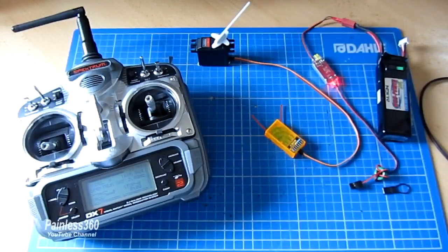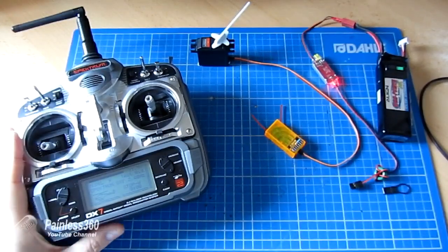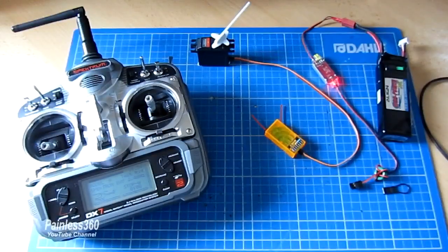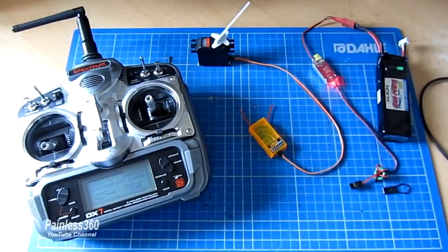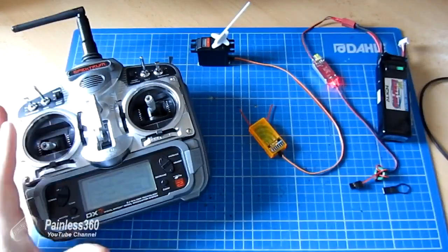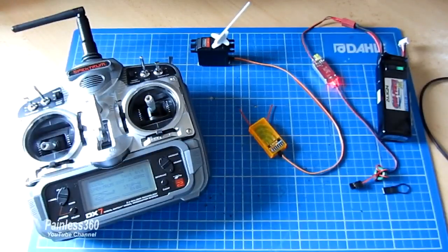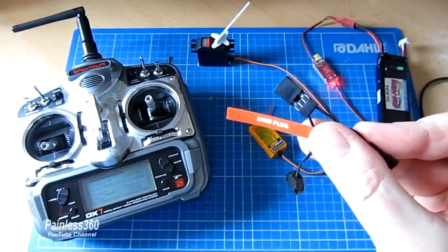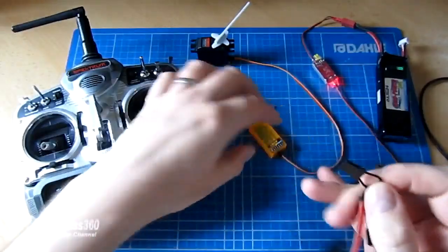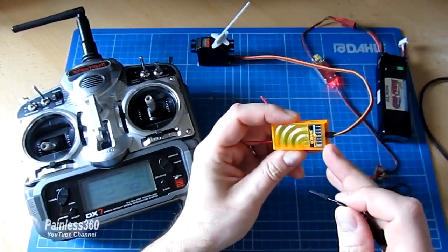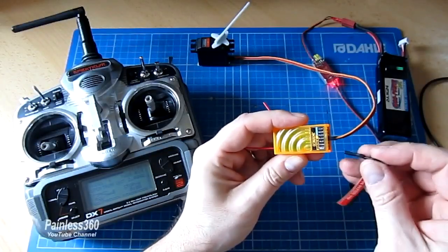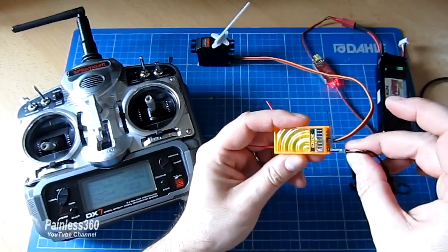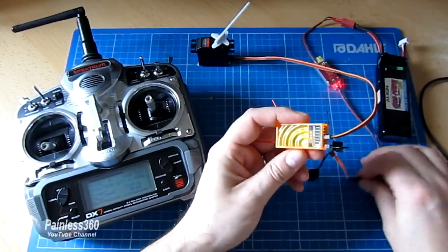We're going to rebind this receiver to the radio, and I'm going to go through the process for Spectrum. Now, every manufacturer's process is slightly different. Look in the manual or look online with the bits and pieces that came with your radio, and it will talk to you about the specific process. But this is how it does for Spectrum, and it's very similar for most other manufacturers. The thing that we're going to need to make this happen is something called a bind plug. Now, a bind plug is a special plug that will go into one of the ports of the receiver, and it's usually clearly noted as battery or bind, and we're going to pop that special bind plug into that port, and then we're going to power the receiver on.